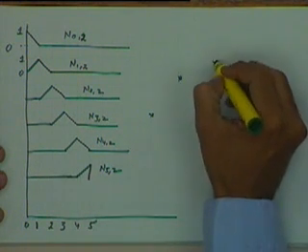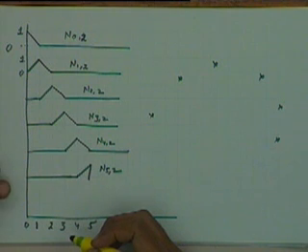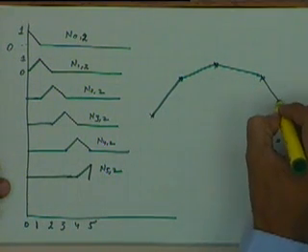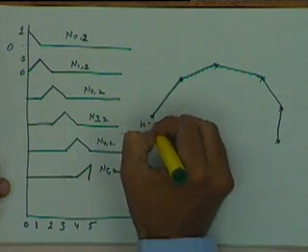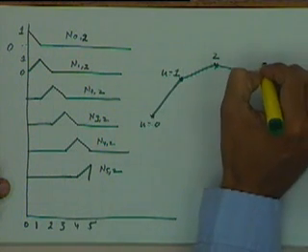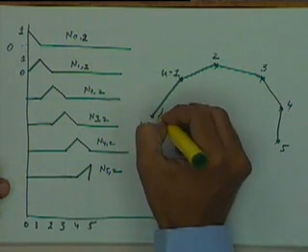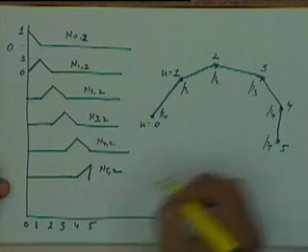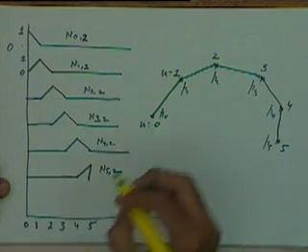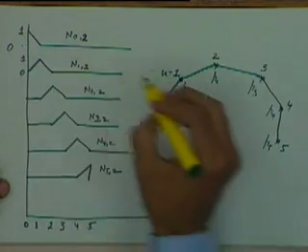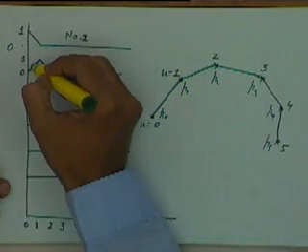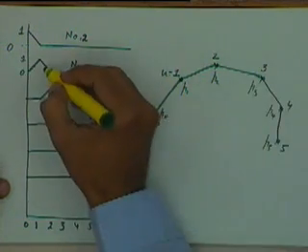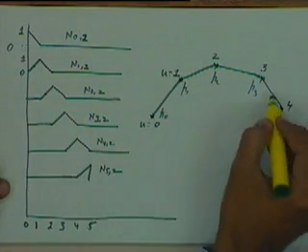Okay, what that means is if you have a set of points, what will the curve look like? This curve will look like a set of straight lines. At this point you will say u is equal to 0, here you will get u equal to 1, 2, 3, 4 and 5. This is the first control point P0, this is P1, P2, P3. So between these 2 points, u equal to 0 and u equal to 1, these 2 points have their effect. So the curve is a linear combination of these two. Okay. Similarly, between these two, the curve will be a linear combination of these 2 points. So we get a set of straight lines.